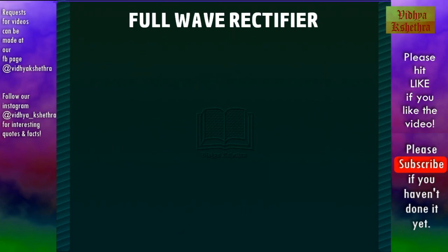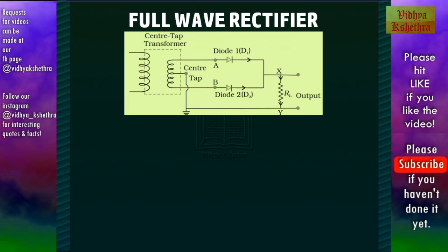Now we can see about a full-wave rectifier. The difference is that in the case of a full-wave rectifier, we will get output for the positive as well as the negative half cycle of the input voltage. For that, we will use a center tap transformer and two diodes. The diodes are connected as shown in this circuit diagram.